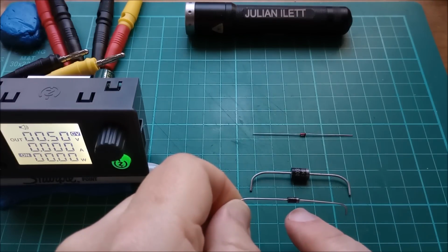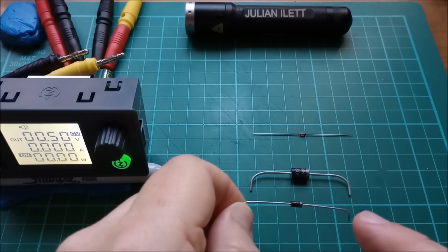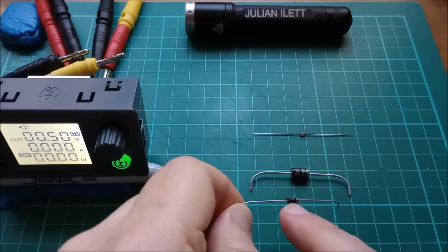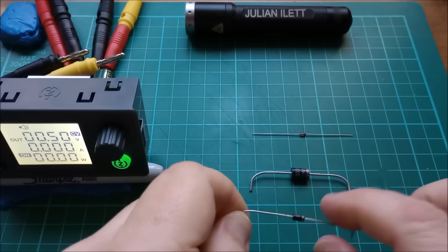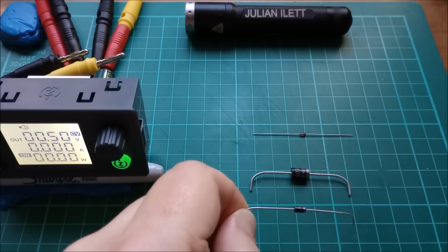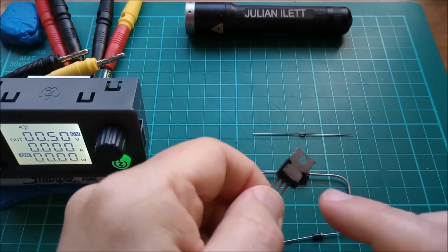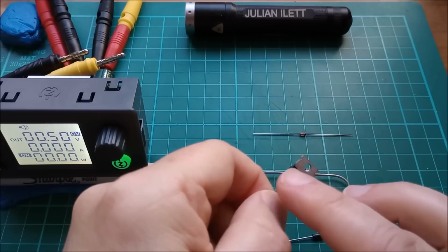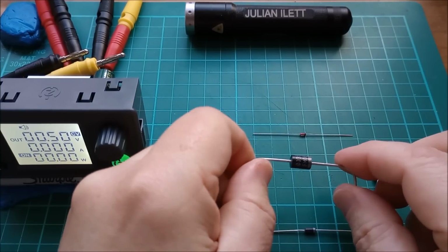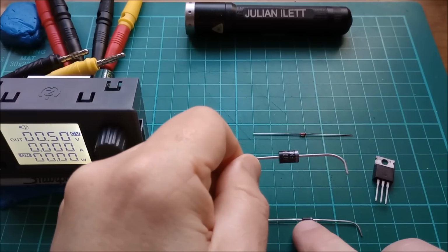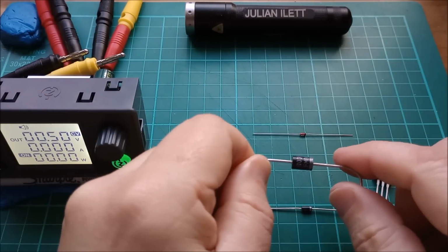That generates heat. That then causes a temperature rise, and an equilibrium is only reached when the amount of heat coming off the diode in the form of radiation, convection and conduction, in this case through the legs, but if you had a TO220 type diode like this, then most of the heat will be conducted through the tab. The forward voltage drop on a Schottky diode is considerably better than a regular silicon diode, about 0.3 volts for Schottky, 0.6 volts for silicon.